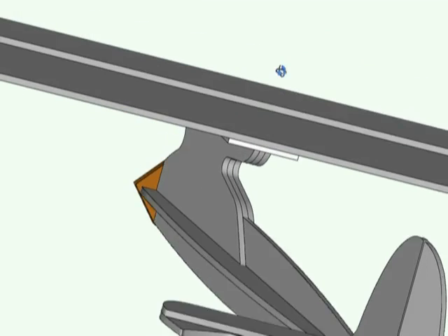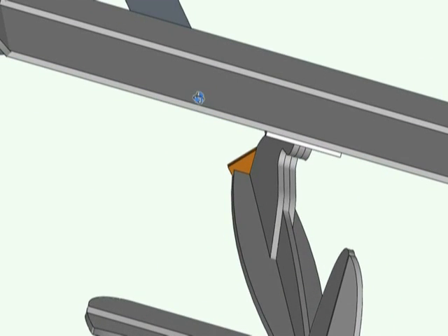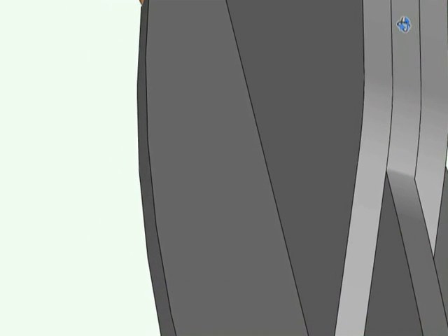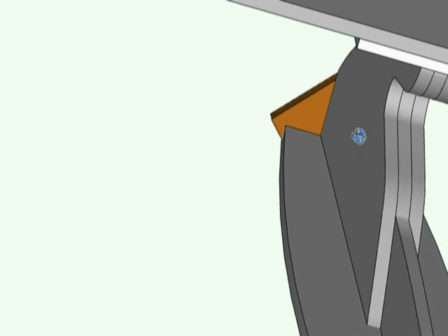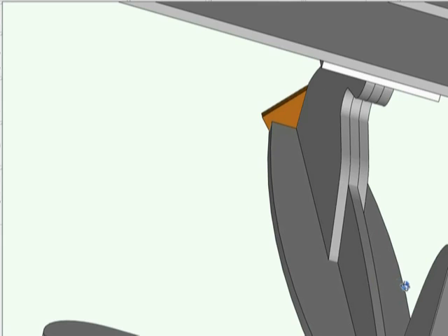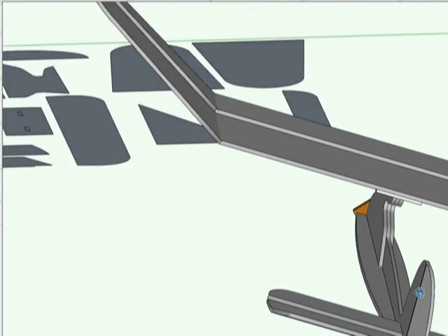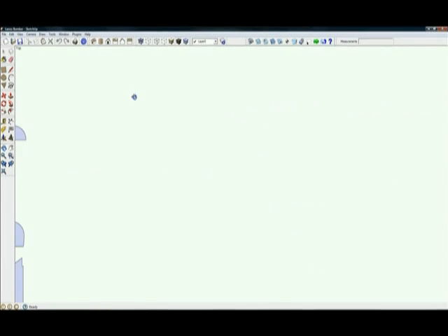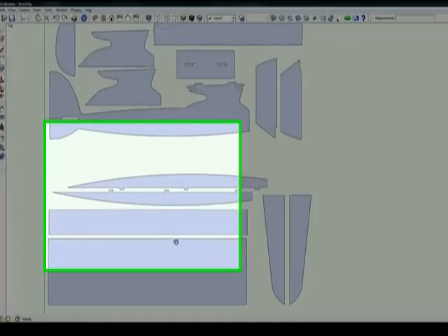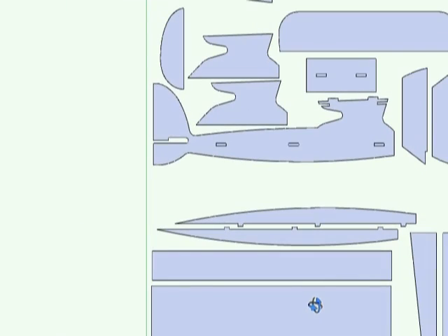I could have made an exploded diagram if I wanted, but here we've got a fuselage that juts up to the wing mount off of a pylon, and then I've got more foam on each side showing how we can make that all a stiffened member. I've got the side parts here, the horizontal bracing, which takes us into some more interesting things. I wanted to talk a little bit about tabs and slots.